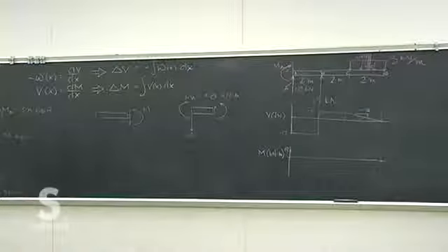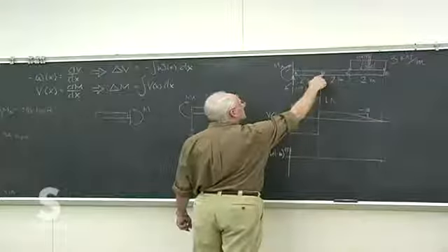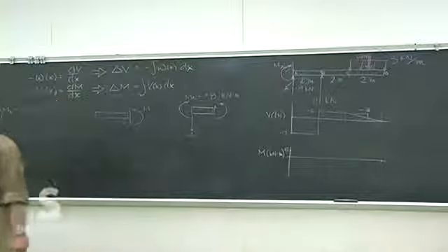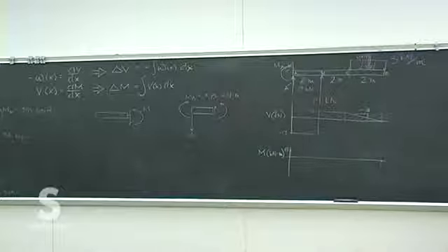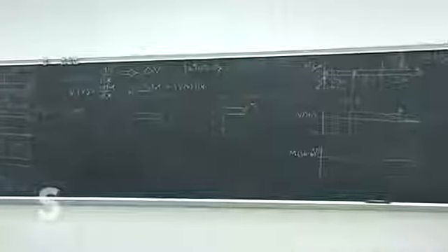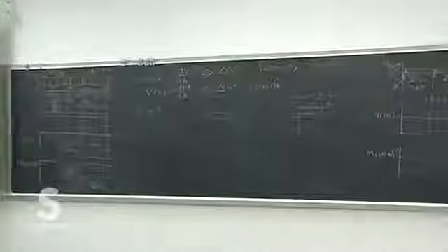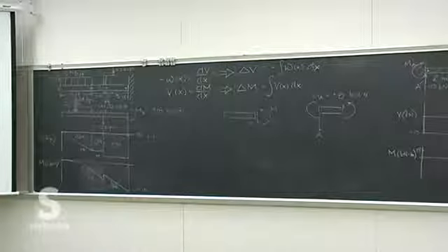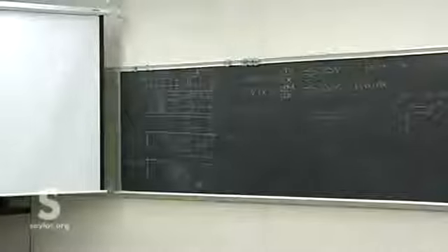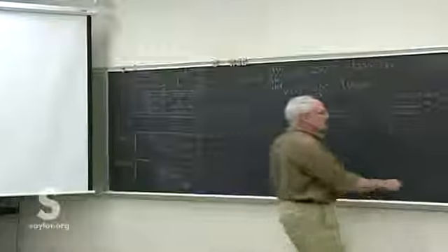No, this upward 19 kilonewton load actually makes these reactions on this cantilever opposite than what you'd normally be used to. We're normally used to everything on the beam pulling it down, but that actually gives it a net effect of going up. It's wrong, but it gets extra credit for creativity. It's an awesome try.